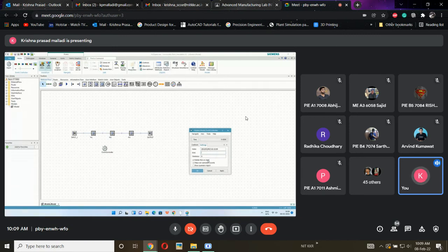I want to run the simulation for 2 hours. 2 hours can be denoted in different manners. You can represent it using seconds, minutes, or directly the number 2. See, if I give 60 and click apply, it will be considered as 1 minute, 60 seconds. I don't like this. 45, apply. Now see, 0, 45, which means 45 seconds. If I give 90, it will be converted to 1 minute 30 seconds.